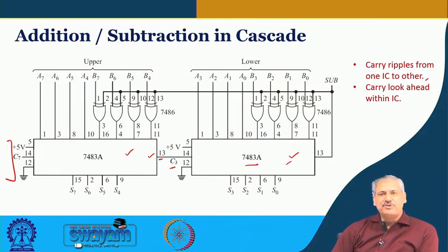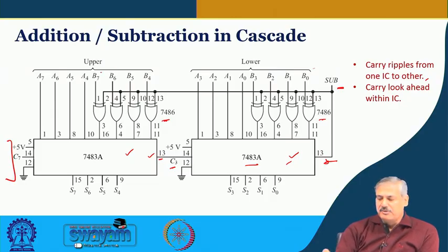And here again we are showing the arrangement of getting both addition and subtraction using the fast adder, and for that we are using the similar approach that we had done before. So, we have a bank of XOR gates here and a bank of XOR gates here, and the sub input is 1 when we are doing subtraction, which adds to the initial carry in the 2's complement of this B7 to B0 number.